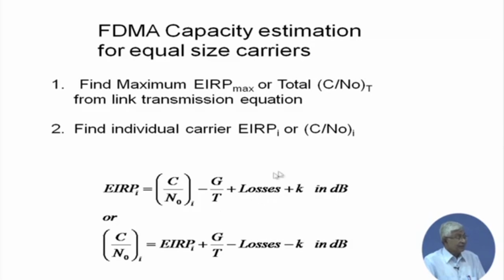As I told you, if the filters are not designed properly, or because of any intermodulation or interference, some of the power will come into the wanted band, and therefore it will increase the noise, and that is where the losses will increase. So our intention is to improve the efficiency, to reduce those interference losses or spurious losses.